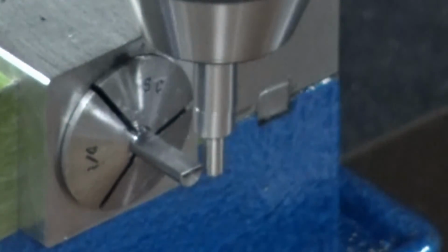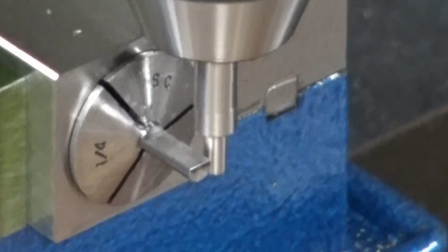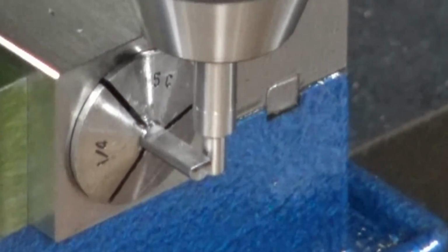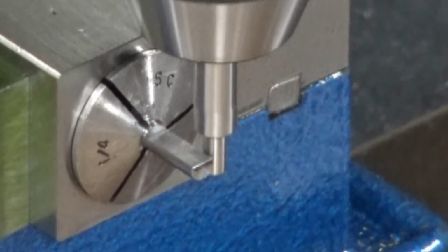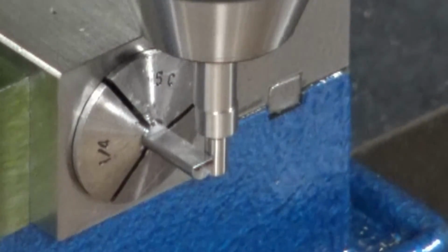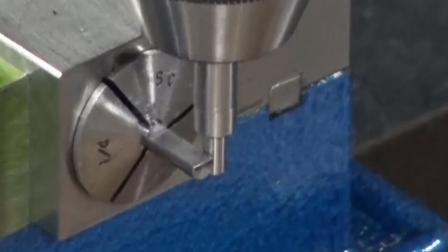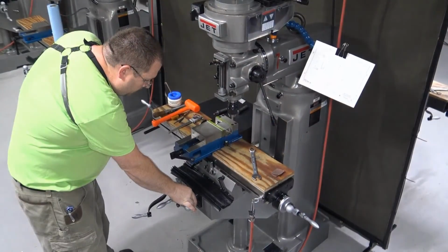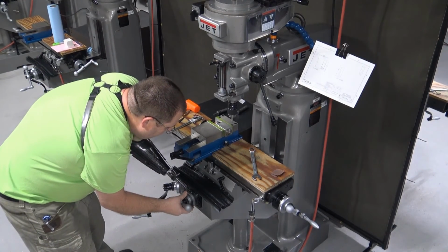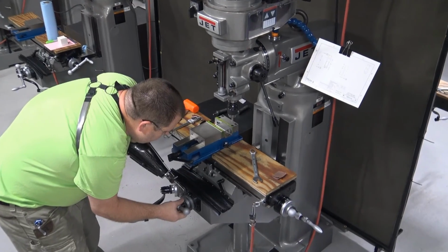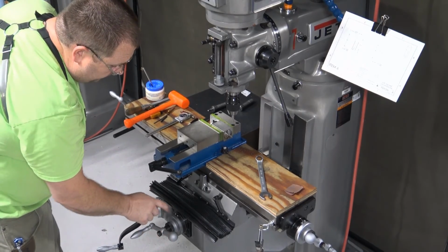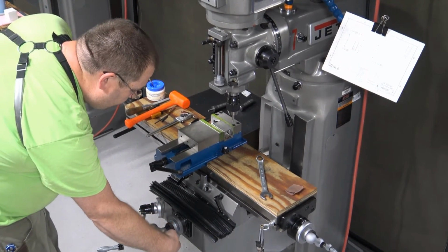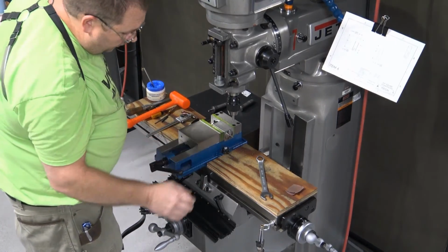Now I'm going to pick up on the outside diameter of that workpiece. Nice and slow, I get a good accurate edge find. There it is. Set my dial to 100. Remember, there's 200 thousandths per rev, so if I set it to 100, I'm going to move at 100. Now I'm at 0. Now I've got to move over the radius of the part.